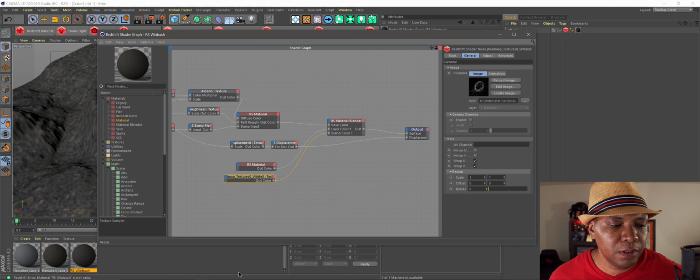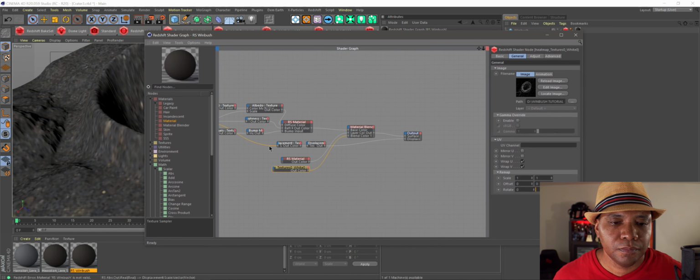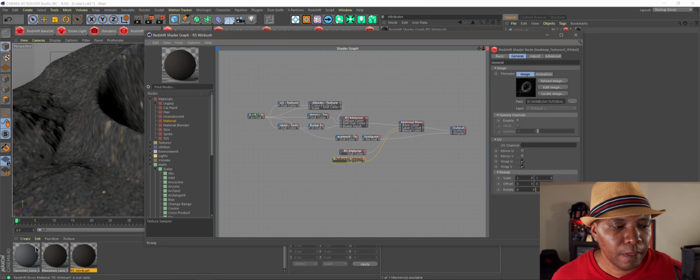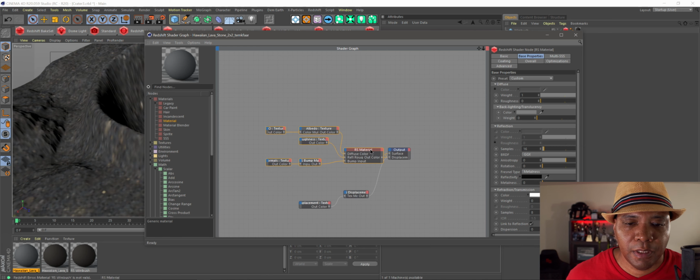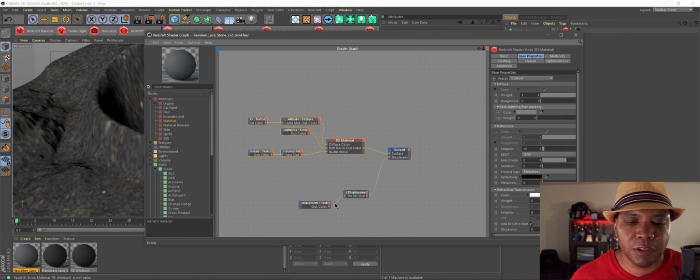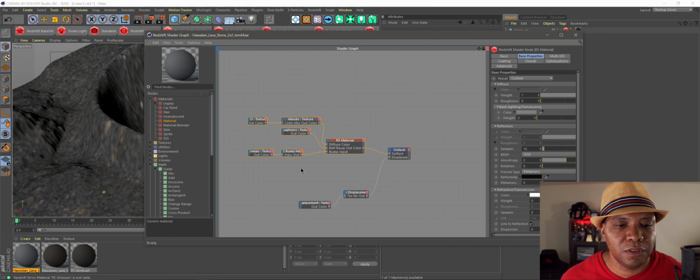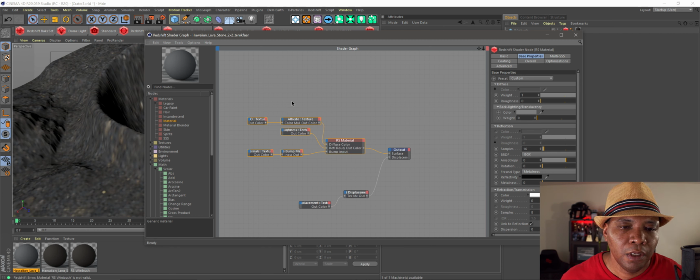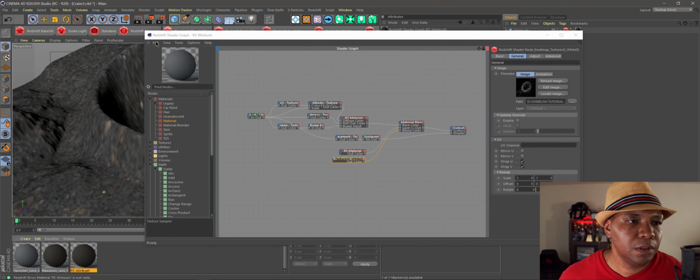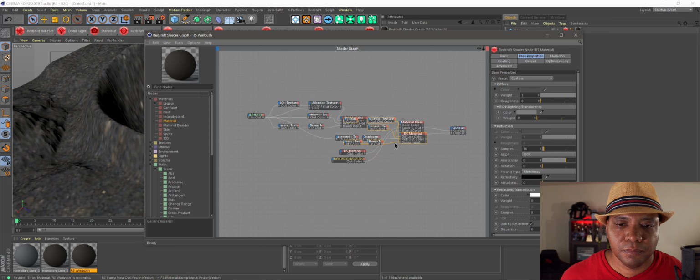I'm going to double click on my WINBUSH original material. Let me zoom out a little bit. I'm going to click back on this other material, and I'm just going to copy the top images here, because I don't think you can do multiple displacement maps. I might be wrong, but I don't think that you can. So we're going to keep the displacement map from our base color, and bring in this top information: our AO, our diffuse, our roughness, and our normal map. I'm going to go to edit, click copy, come to my WINBUSH material, go down to edit, and click paste. And then let me drag this down here.